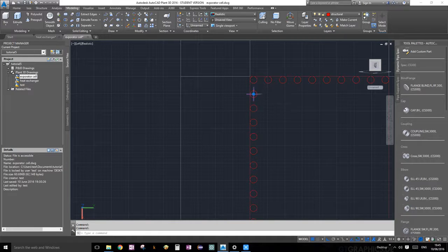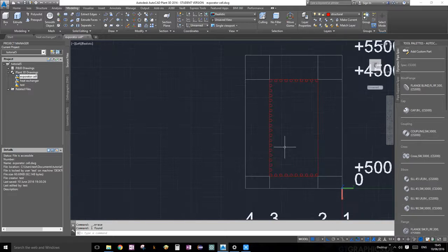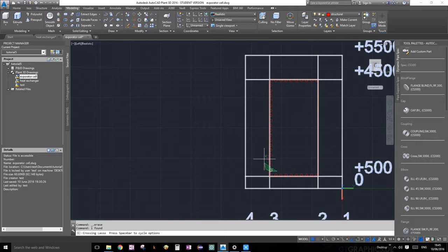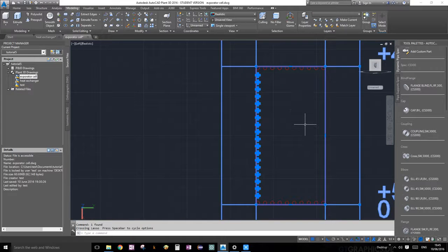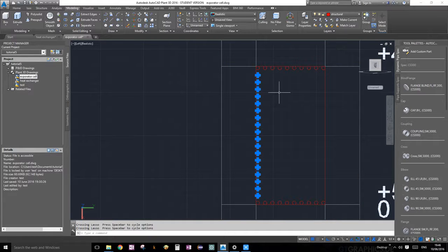So now the next thing we need to do, we're going to select all of these ones that we just drew, and we're going to mirror them again. So I selected all of them, but in the same process it selected everything else that it crossed. So press and hold shift and use the green button to choose whatever you want to unselect. Perfect. Now we're going to mirror. So let's go back to modify, mirror, and we want to mirror along this line.